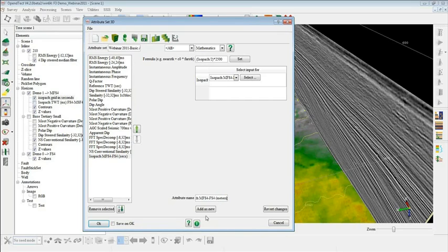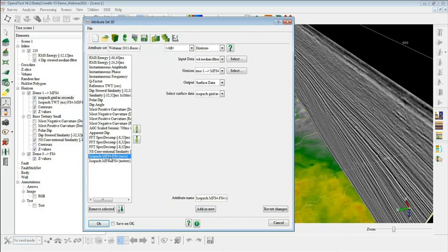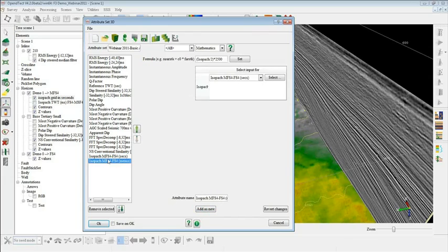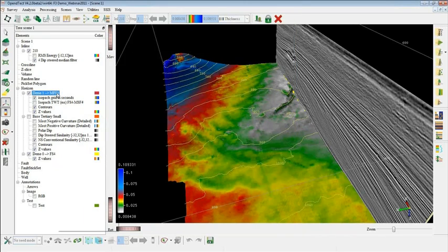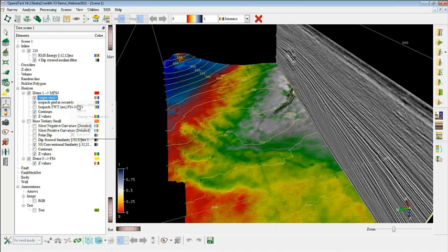So you press that. In this way we have used two new attributes, one is horizon, the other is mathematics. We wrote a simple equation there, and now we are almost done. We simply need to calculate the isopach map in meters on the horizon that we were looking at previously. Press OK, and I add as new, and I run this on the fly.